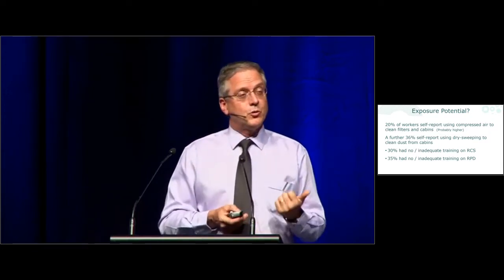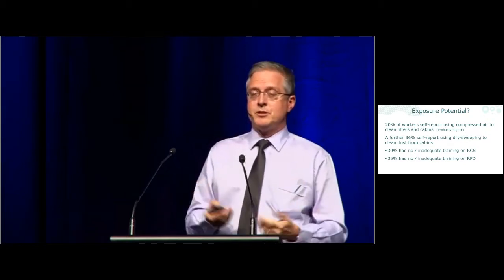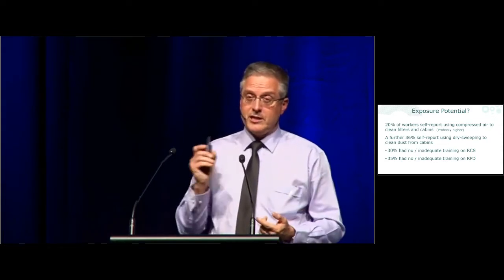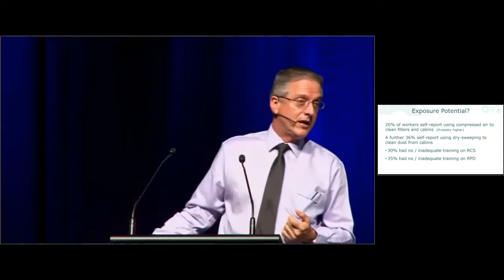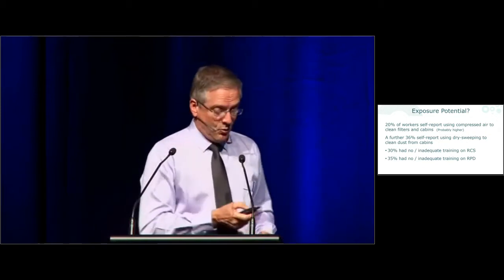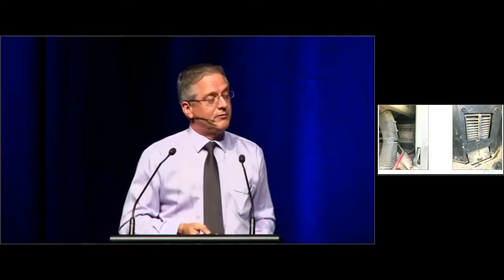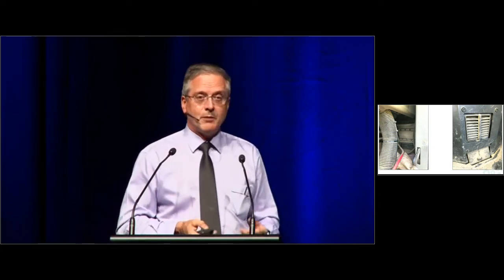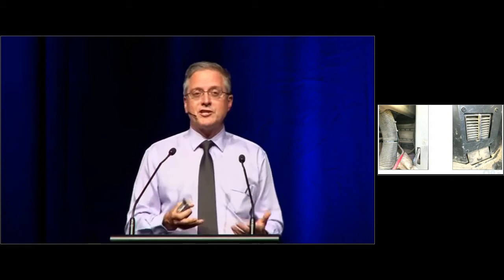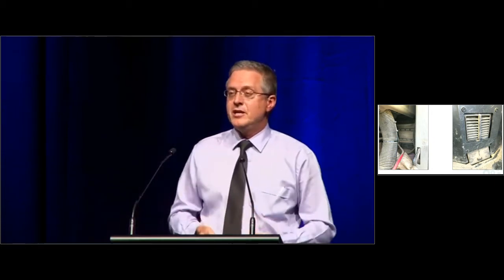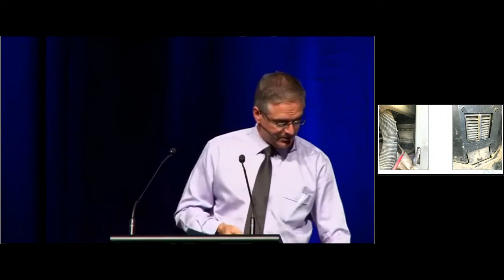Many of the guys that I talk to about blowing out cabins, when you ask them, how do you stop yourself breathing the dust in, and this is not a joke, they say they just turn their head away and hold their breath. That's how they control their exposure. We saw earlier on, and I'll have a repeat of a slide that Peter Aspinall had up before. We'll see why that's not effective once we have a look at particle size and suspension, how long it stays suspended in the air.